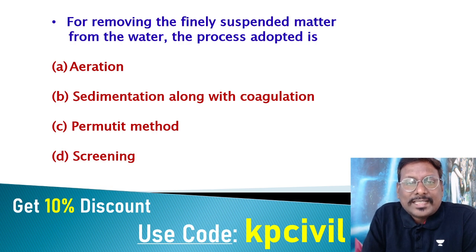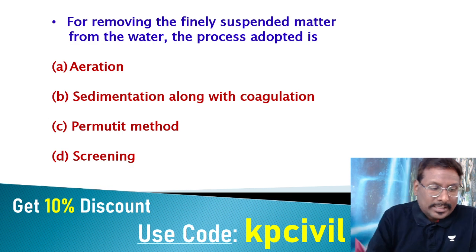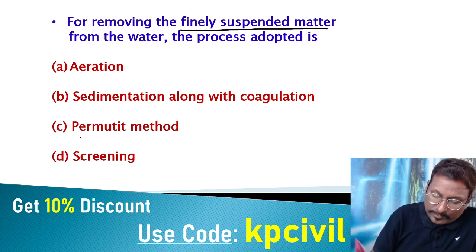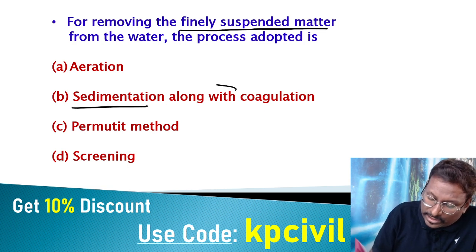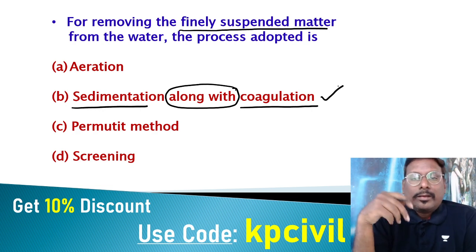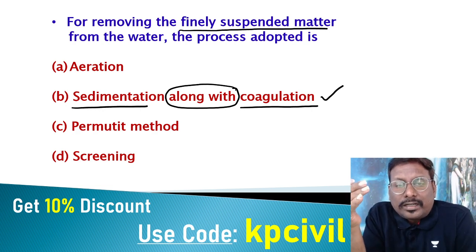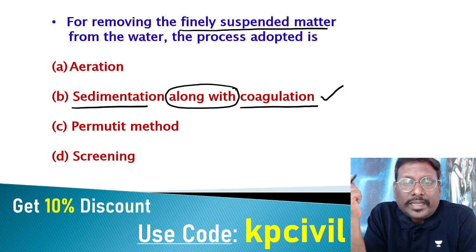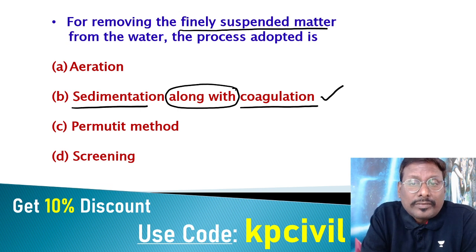Removing finely suspended matter from water: fine suspended solids, finely suspended matter, sedimentation along with coagulation. Because aeration is for removal of dissolved gases, increasing DO, removal of color, odor, turbidity. Screening is for floating matter. Fine suspended particles need sedimentation along with coagulation.